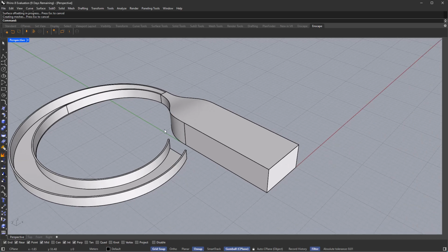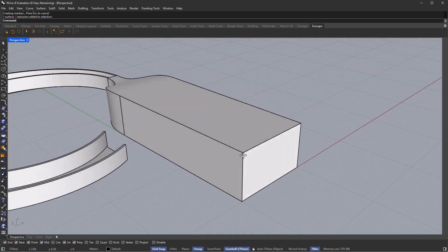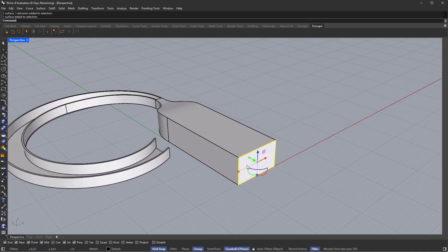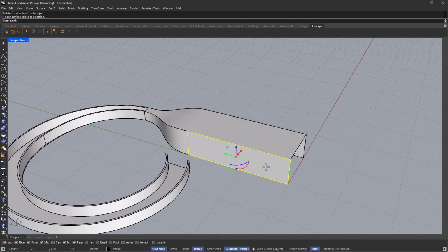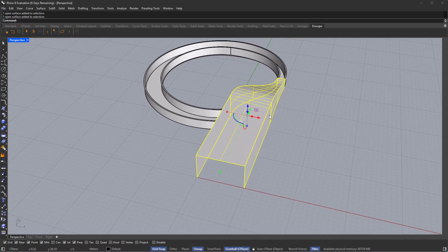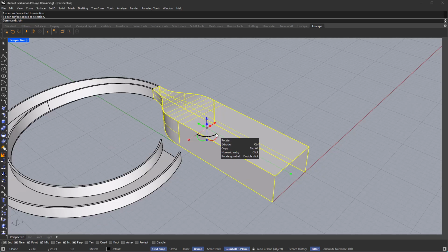twice. Now, because this volume is going to be our entrance or our axis, I need to delete this surface. To select individual surfaces in Rhino, we need to use the Ctrl plus Shift keys like so. Now select all of these surfaces, make sure that they are joined together. So you can select multiple surfaces with Shift and then type in join.